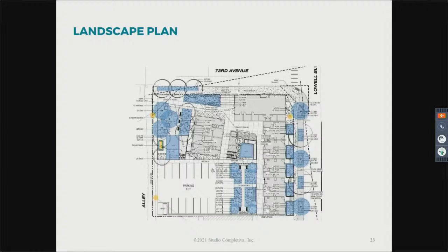Okay. Is there a storm drain in the alley, or does it have to make it down to 72nd before it would hit the storm drain? It does have to make it all the way down to 72nd at this time. Most of that grade break is really at the northern portion of the alley, right at 73rd, and then everything rushes down there.